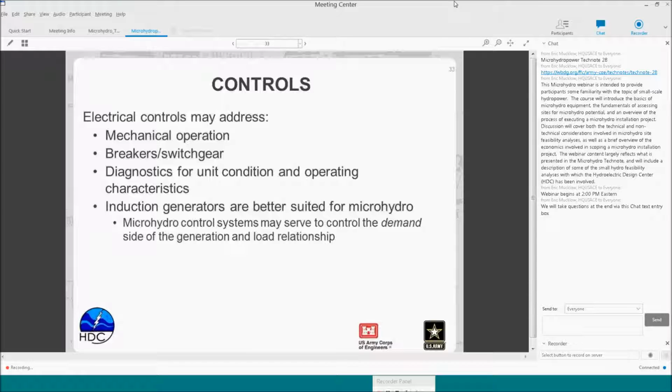With microhydropower, it might be more beneficial to allow the turbine generator unit to run simply at its design output and add controls that change where the electrical output load is applied, connected to the grid or to a battery bank, or interchangeably based on the on-site electrical power demand of the facility where you're setting this microhydro unit up.